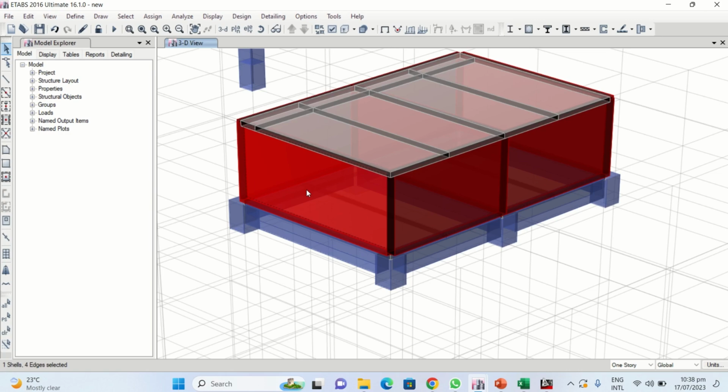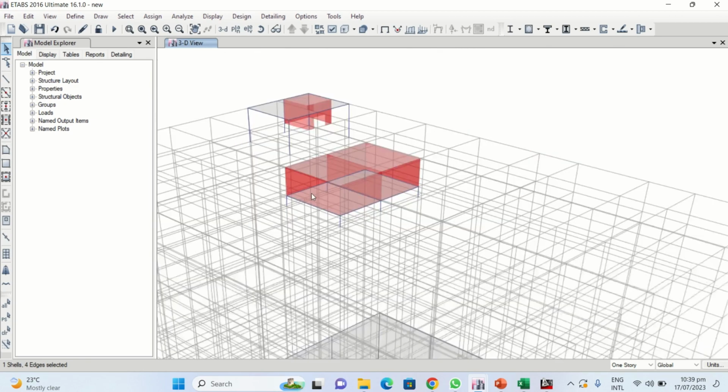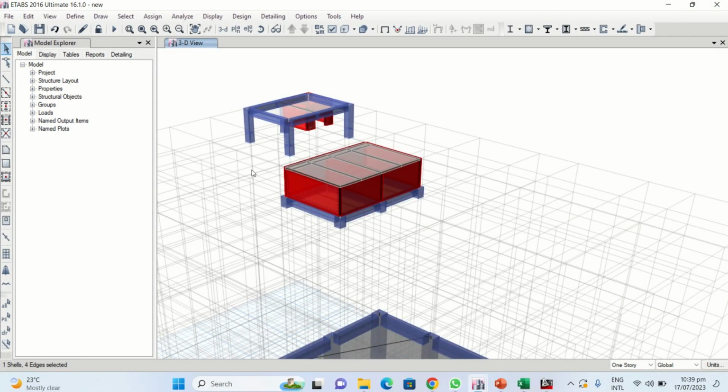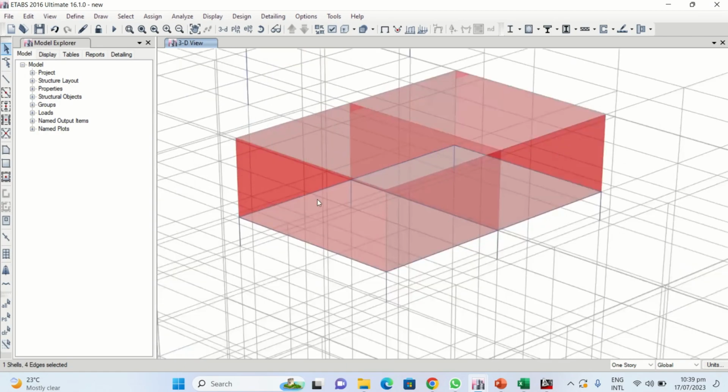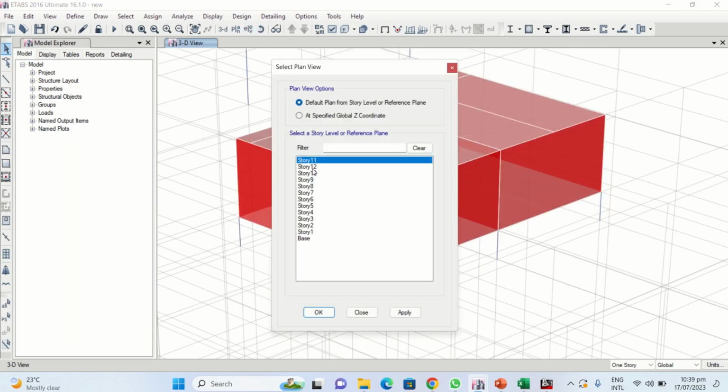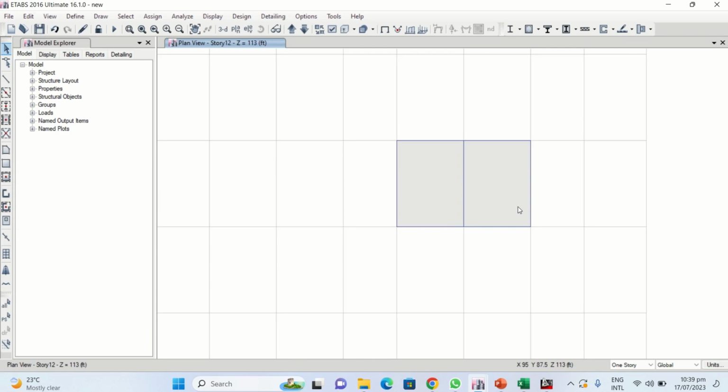But we do not want the water tank to be a complete part of the structure resisting system. You can do it as a case study, because if you take the load on the walls as a live load, it will cause many issues in the structural design. So we will take the overall gravity load of the water tank in order to calculate the seismic forces, base shear, based on the live loads.